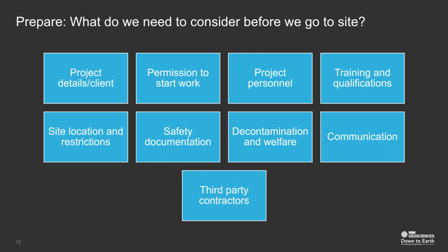The BDA, the British Drilling Association, is the UK's trade association for the ground drilling industry. In 1992, they produced a guidance document for safe intrusive activities on contaminated or potentially contaminated land. And this introduced a site classification system: green, yellow, and red. Green being your simple sites. So I say simple, simple is probably the wrong word. Green being your less risky sites.